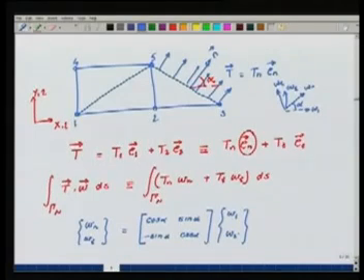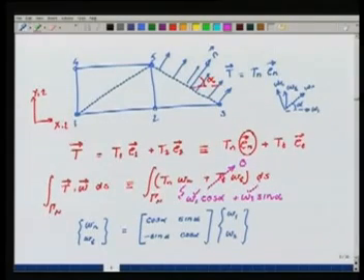Remember, I am talking about the function defined on this face, the face which is this inclined face. Okay, so now it's very easy to put the boundary condition, because here, for example, my t is 0, so let's knock this off. Wn will now be given as W1 cos alpha plus W2 sin alpha. Okay, and we have defined our W in terms of the Cartesian coordinates, that is, in terms of the components W1 and W2.